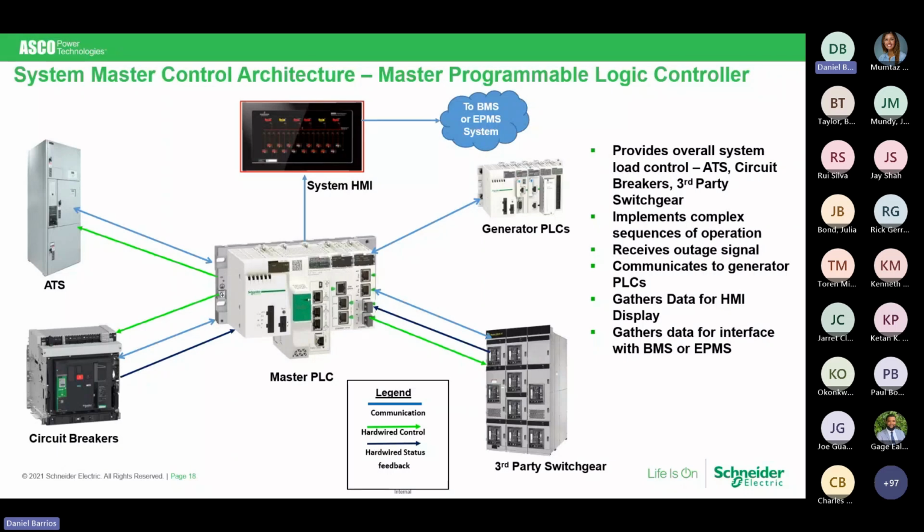A very important point with that is the fact that if you are working with automatic transfer switches along with the paralleling gear, you have a remote annunciator somewhere in your facility from each of your generator sets required by the NFPA, whichever one you have applicable.